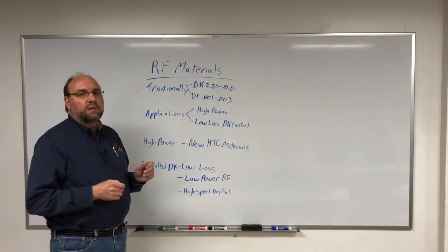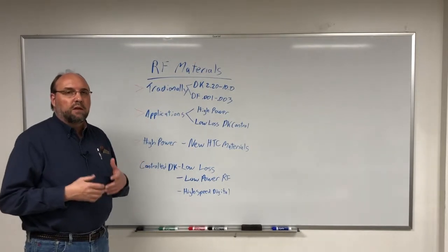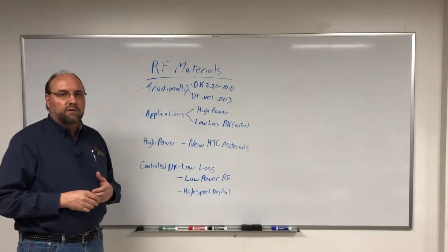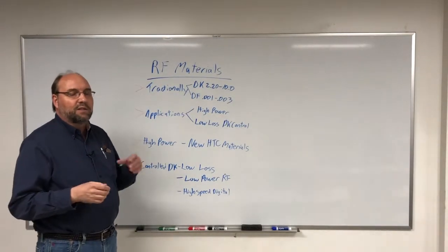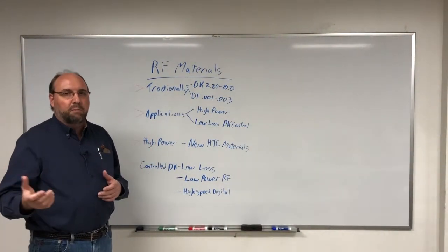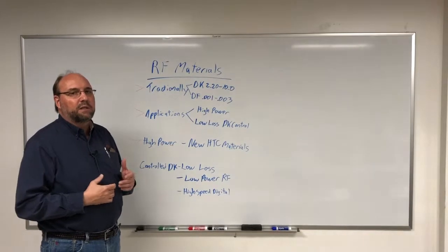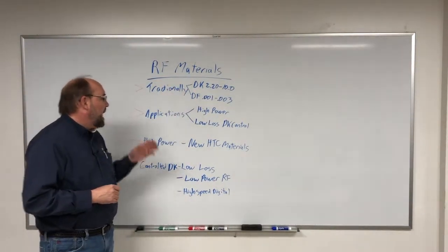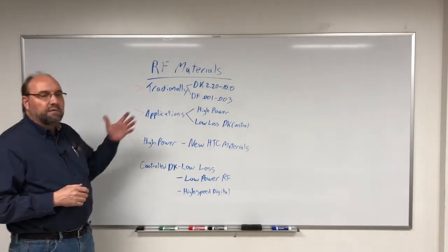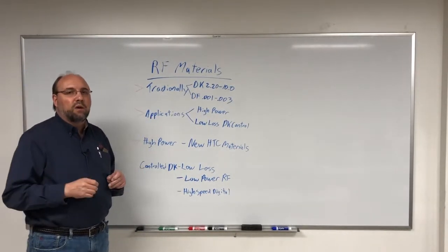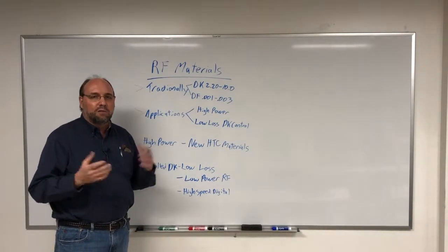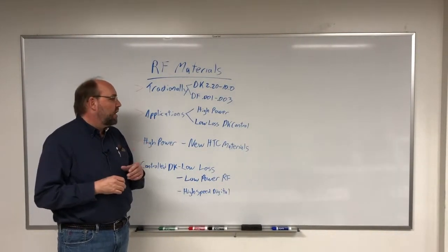In the past, those materials were Teflon-based, usually required special processing, but with the advent of new material creation within the last 20 years, there's been hydrocarbon materials, PPO materials, PPE type materials, which have started to reach into these performance levels. Applications in general have been either very high power or very low loss. It doesn't mean that you don't need high power and low loss. Of course, that's usually required as well.